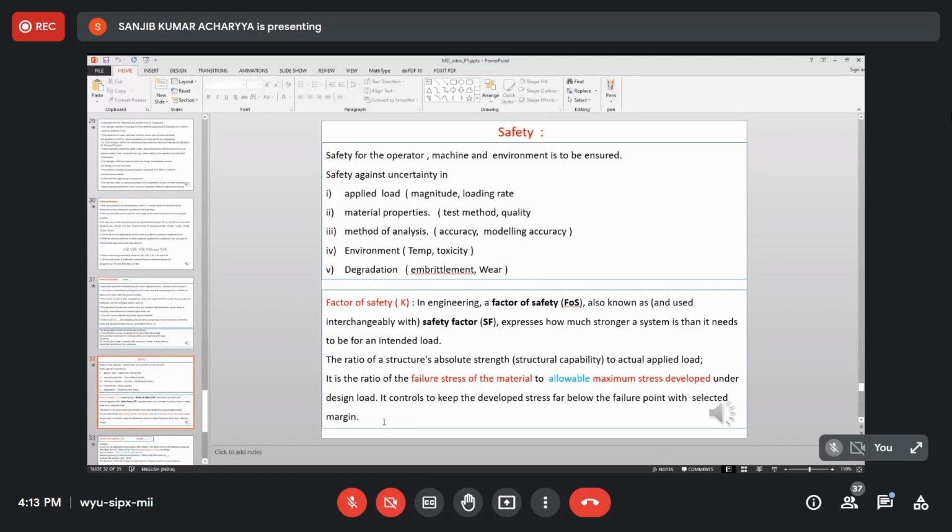Yes, sir. And safety of the product is introduced by introducing a factor named factor of safety into design. What is the factor of safety? Factor of safety means that by your material testing, analysis, every scientific approach, you can evaluate that the maximum applicable load of the member is 1000 kg. But actual application of the load should be below that to ensure the safety, isn't it?